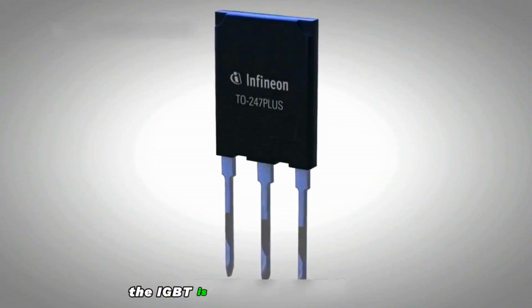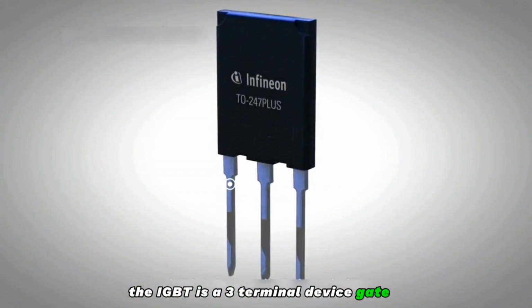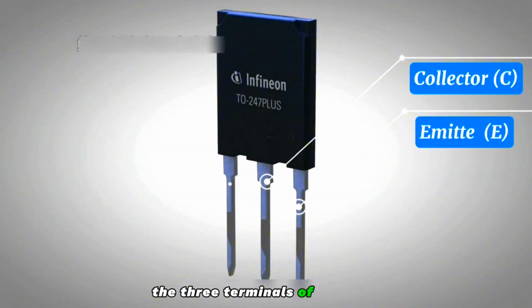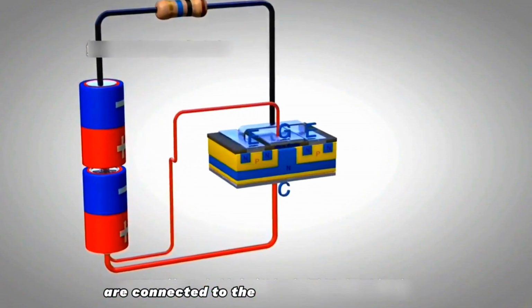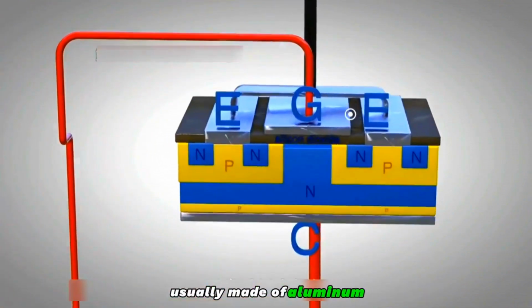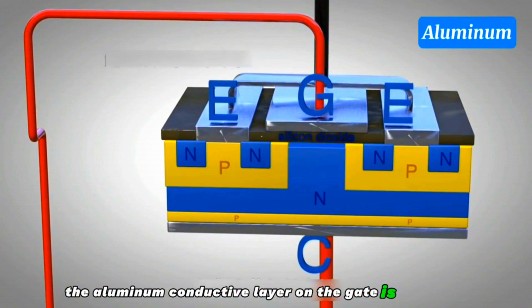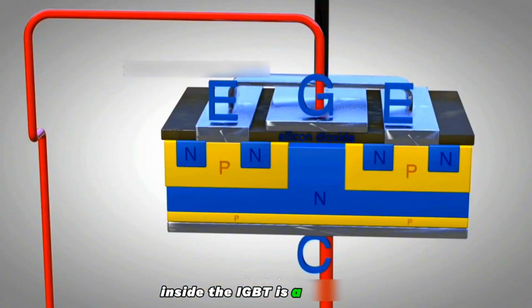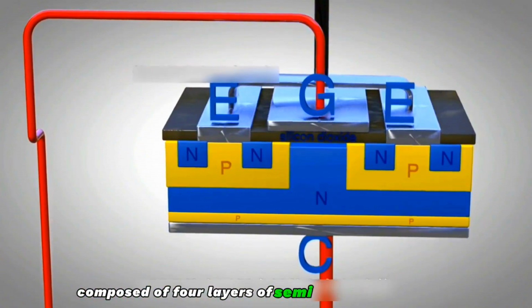The IGBT is a three-terminal device: gate (G), collector (C), and emitter (E). The three terminals of the IGBT are connected to the metal conductive layer usually made of aluminum. The aluminum conductive layer on the gate is insulated by a silicon dioxide layer. Inside the IGBT is a collector composed of 4 layers of semiconductor material.